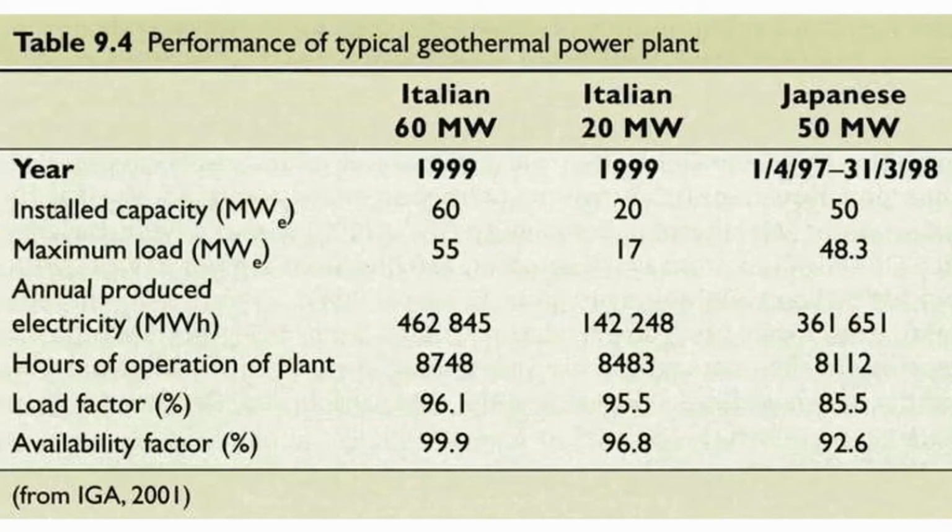That means you have a very high load factor, or capacity factor, of 96.1%. And the availability factor, where you could theoretically use the power plant, since sometimes you don't need energy, was up to 99.9%.